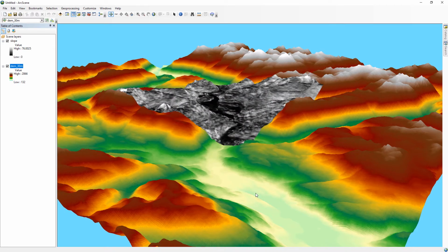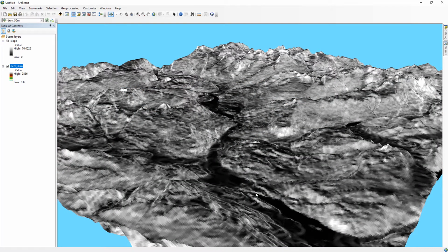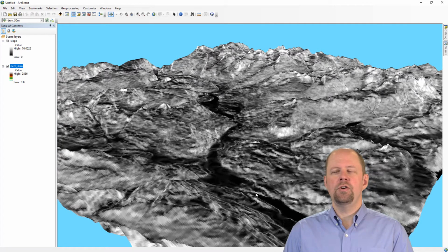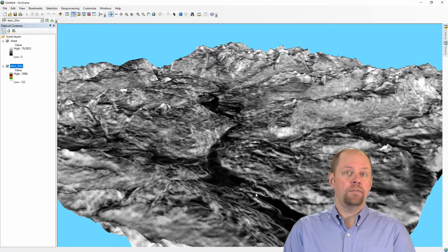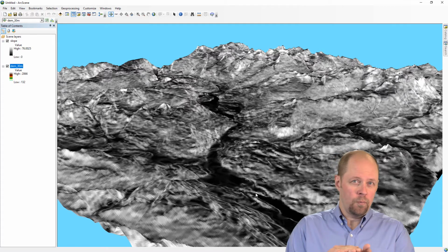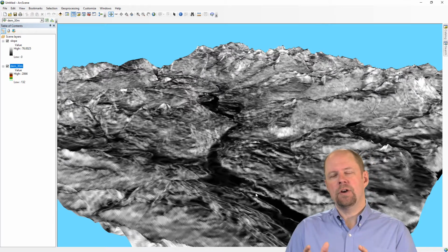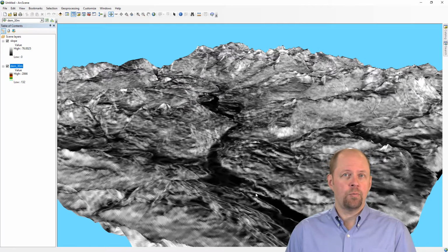Click OK. And so now you'll see that what's happened is that it's saying, oh, the slope data has a higher priority when rendering, so that will be done first, it will be on top, and the base map data will be underneath. There's other ways to do this. You could, for example, add, say, 1 meter to the slope values of the base heights in order to raise it up slightly. Sometimes that trick works as well. This seems to have worked pretty well here, so that's fine. That's all you really need to do.